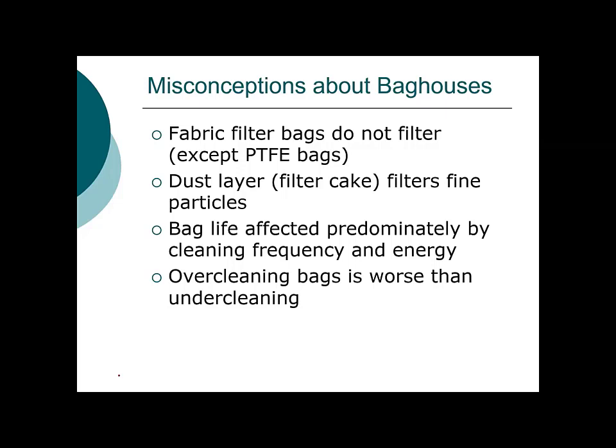The bag life is affected predominantly by cleaning efficiency and the energy that's used in cleaning. The more frequently you have to clean, and the more energy you have to apply when you're cleaning, the shorter the lifetime of that bag. And these are expensive, as you can see. You can imagine what the cost would be for 6,000. Over cleaning bags is actually worse than under cleaning because of the impact on bag life.